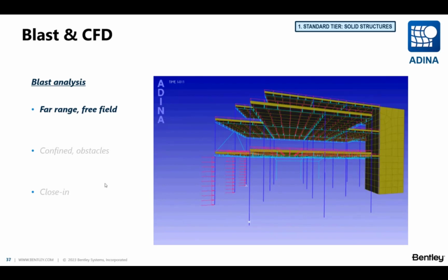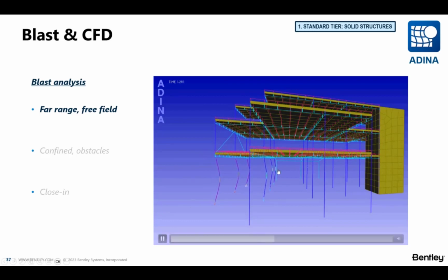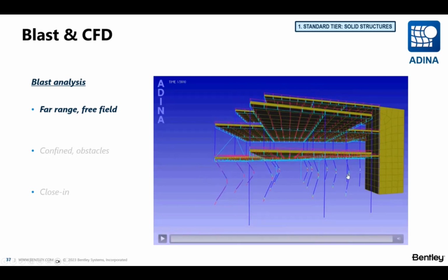In this example, however, we see again these pressures to this side of the building structure. Again, they will be of very short duration, very few milliseconds, and very high intensity, and we're going to see that these columns fail as a result of that, but we're also going to see what happens to the rest of the structure. So we see how, as columns can't really cope with the vertical weight because the first row of columns is failing, that load is transferred to the next columns that continue to fail and buckle. So that progressive failure is something we capture.